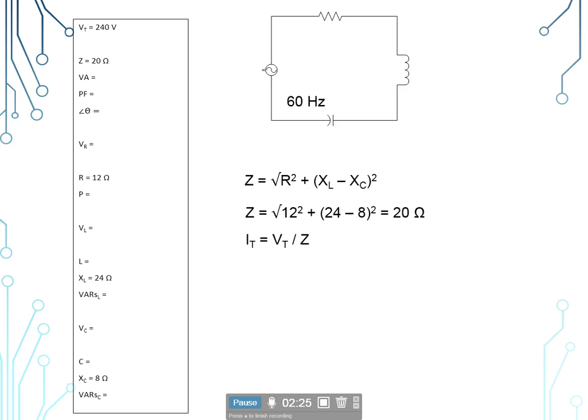Now that we have our impedance, we can find our current total using Ohm's law. So our current total is equal to our voltage total divided by our impedance. So our voltage total of 240 volts divided by that 20 ohms will give us 12 amps.